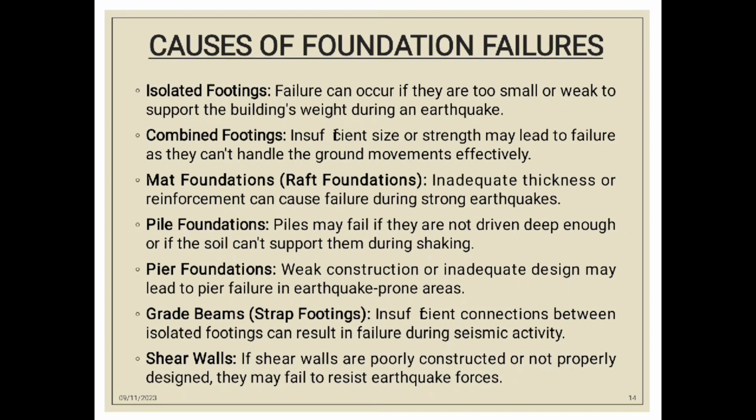Grade beam, strap footings: insufficient connection between isolated footings can result in failure during seismic activities. Shear walls: if shear walls are poorly constructed or not properly designed, they may fail to resist earthquake forces.